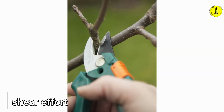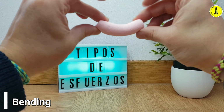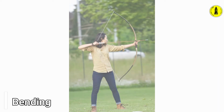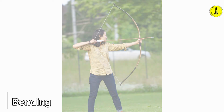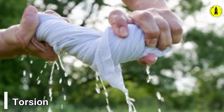A shear effort attempts to break or section a material by applying forces parallel to its section and very close to each other. Bending occurs by applying forces parallel to the same direction, but this time are very separated from each other. A bending effort attempts to bend the longitudinal axis of a part. Torsion attempts to twist the material around its longitudinal axis, but without bending that axis.